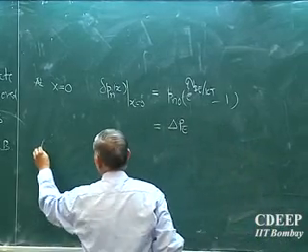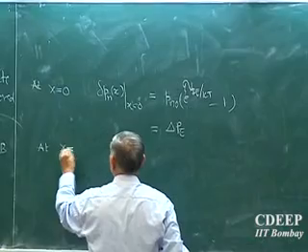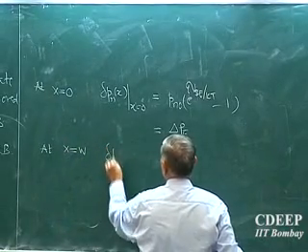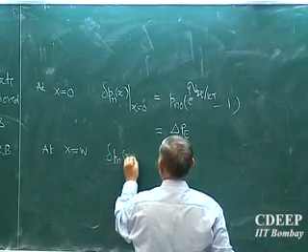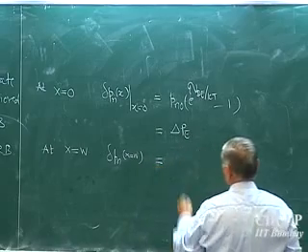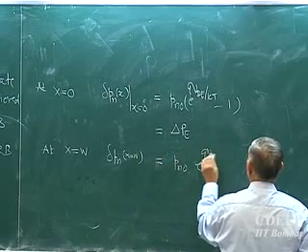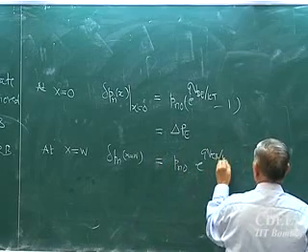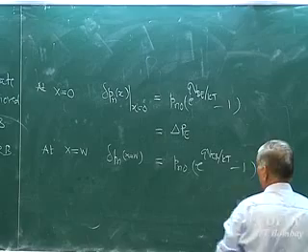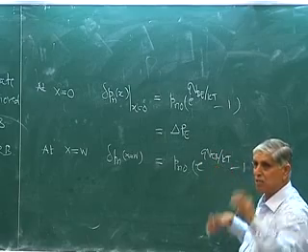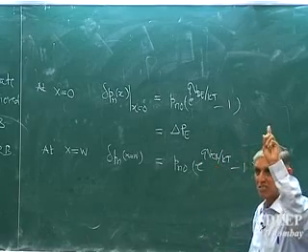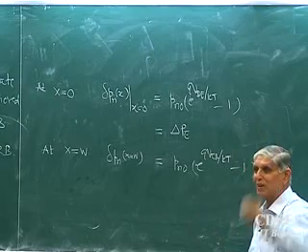By similar argument, I say at x is equal to W, delta Pn at x is equal to W can be written as Pno e to the power q VBC or VCB, whichever way you write. Please remember this, I may write VBC wrongly sometimes. Please in reality place the correct signs, because minus means it should appear as minus.